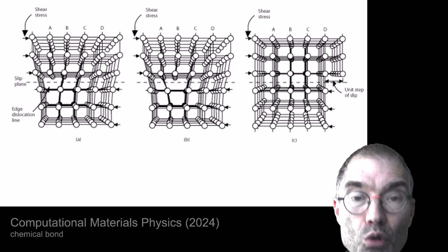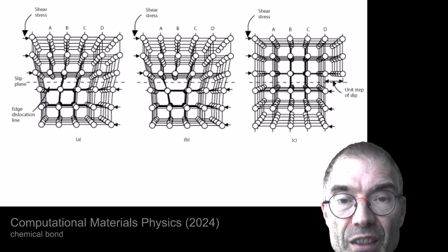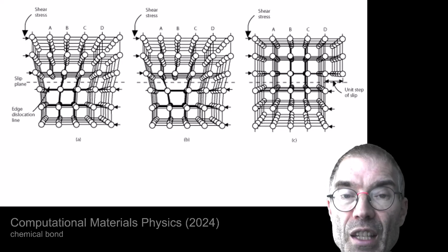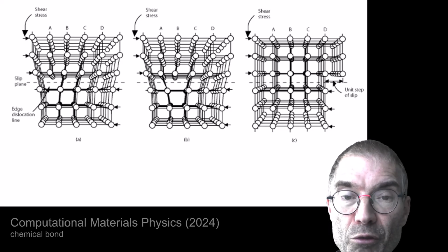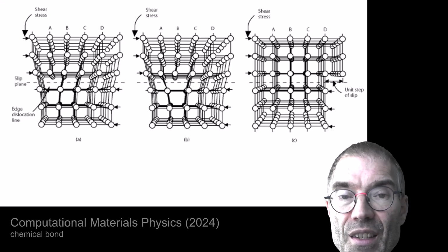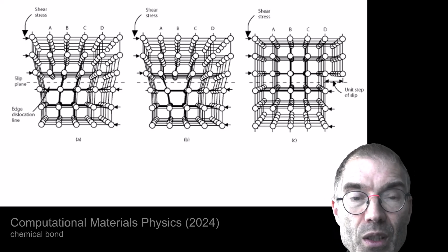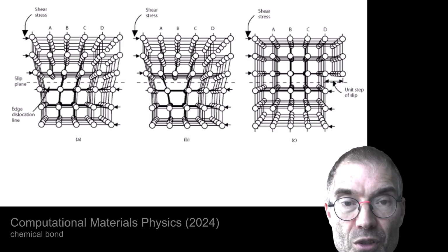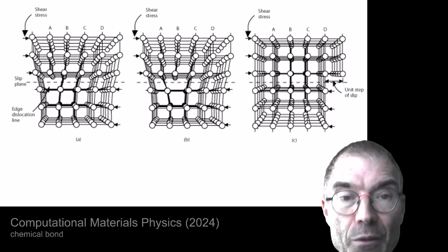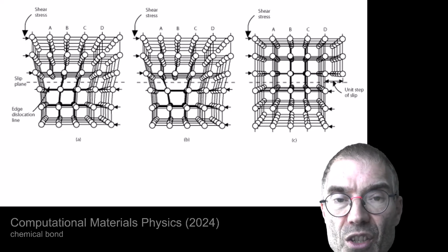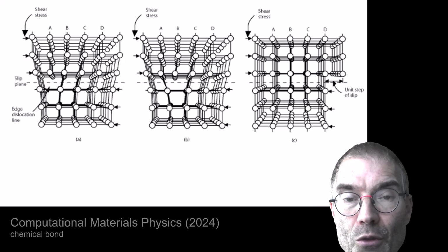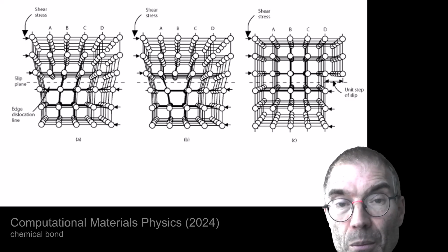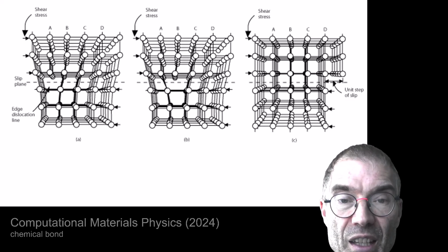You can look at brittleness, at non-ductility, also this way, and this effect does play an important role. If dislocations can easily move in a certain crystal lattice, then this crystal will be ductile. You can deform it because the moving dislocations will give way. If these dislocations do not move easily in a given direction, then the crystal will break instead. It will be non-ductile.